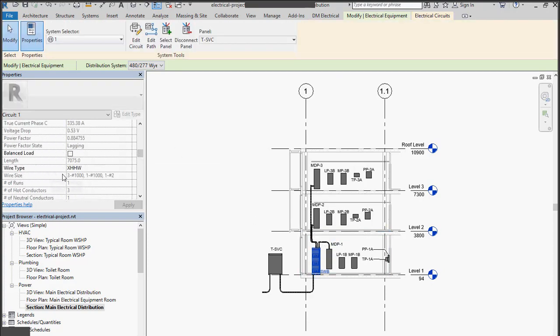So the circuit this is connected to has in Revit a wire type and a wire size. They are wrong, not set by our software, not used. Revit doesn't give us the ability to change or set those. So Revit says, this is what I think the wire size is. I hope you're happy with it.